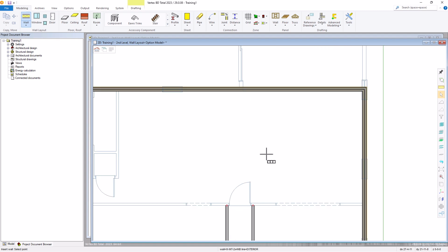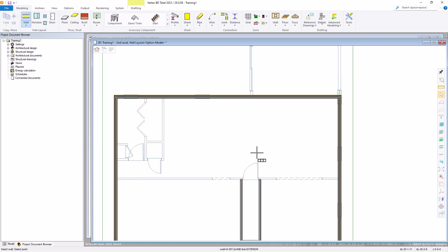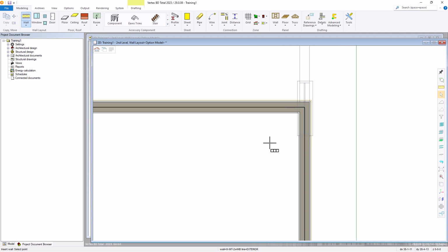Now we have some other walls that we need to add, obviously. We'll add the other walls with the aid of the Q reference tool. We'll clean up any intersections later that we need to. So let's start with this horizontal wall that we have. We have a wall that's going to come out 8 foot 10 inches down from this corner.